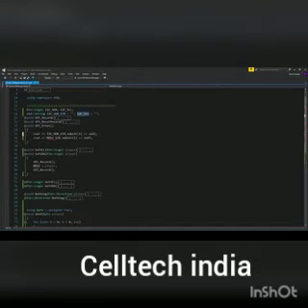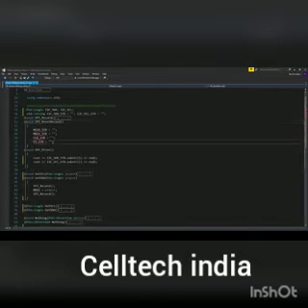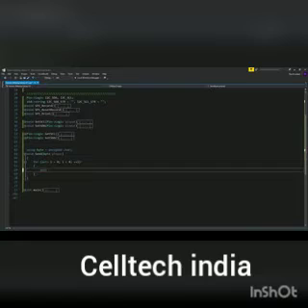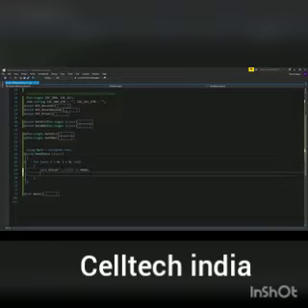So I'm just modifying the SPI code, just to make the names and logging system make sense. The way I actually do this is by having, before and after any change of a pin, I basically just record the state of all the pins. And that's all I'm doing here. That allows me to plot the data and see the relative change between each of the pins, assuming that there's no noticeable overhead from program execution.